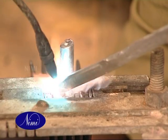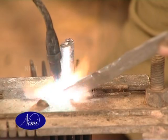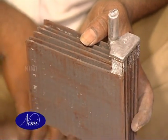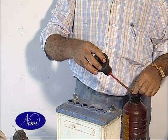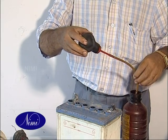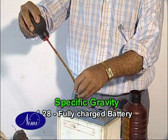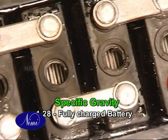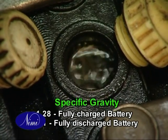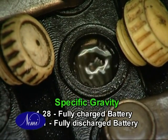Post terminal. A small pole extended upward from each group of welded plates from the plate connector forms the post terminal. Electrolyte. The electrolyte used in a lead acid cell is dilute sulfuric acid. The specific gravity of the electrolyte is 1.28 in a fully charged battery and 1.1 in a completely discharged battery, with a variation of 0.01 in both cases.